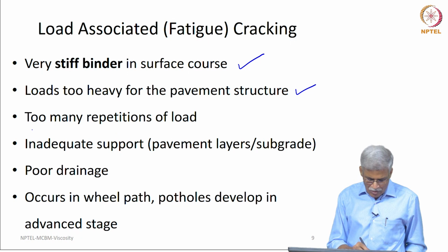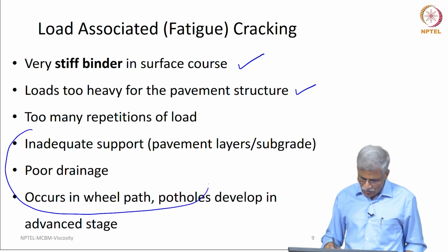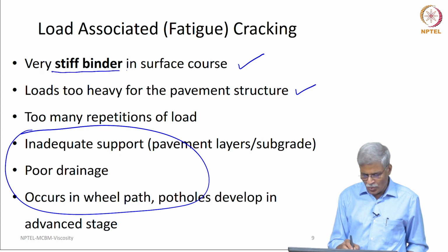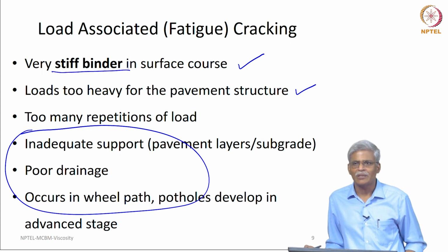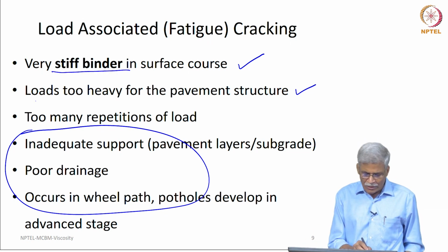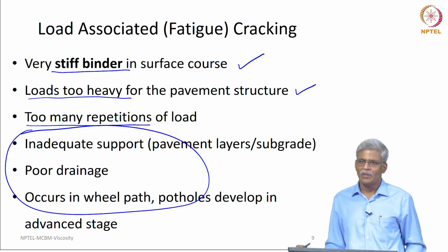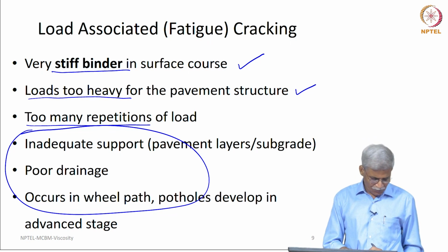The rest of the things will not be discussed here. So, you are going to have a very stiff binder in the surface course, and the loads that are too heavy with too many repetitions of the load. So, this is the reason for your fatigue damage.